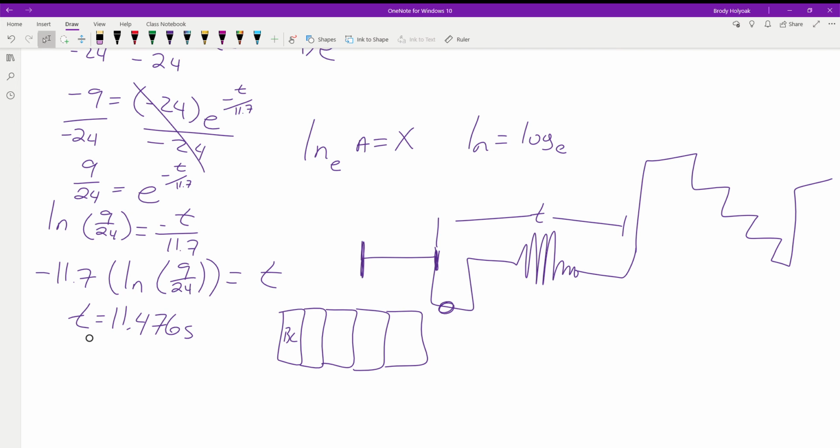You want everything downstream to have a delay until you can initialize all your chips. You say this chip starts out at 0, this bit starts out at a 1. You don't want random things to happen. As this thing is delaying to turn everything else on in your system, it's going through and saying, I want everything to be shut off. Because once in a while when you turn on the chip, it's going to say, you are on. Well, what you're telling on could be the shredder that somebody's working on. It could be a robotic arm that's going to swing and whack them in the head. So you want this delay to make sure nothing is being told to move and nothing's moving after a delay.